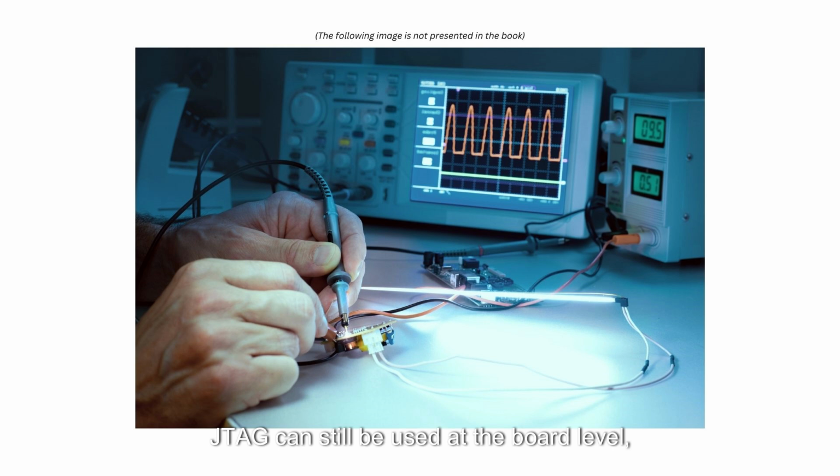JTAG can still be used at the board level, but it does require the PCB designer to add this functionality into the design. In addition, only components that have JTAG ports can be chained together. To conclude, there are other tests, many of which assist in debugging, or to obtain analytical data such as propagation speed, operating temperatures, current draw, etc.